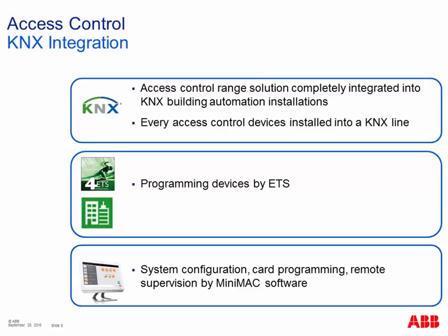So the devices, as I told you before, are programmed by ETS, the standard software for KNX. And last, the system configuration is then performed by MiniMAC. So after having programmed the device with ETS, it's possible to program the device in the MiniMAC software, which is the access control software for creating the installation.